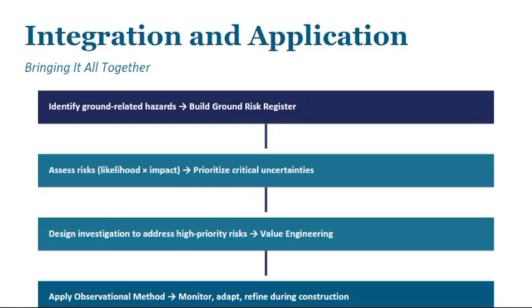case study, for example, of a proposed high-rise building on reclaimed coastal land. So this is the case study. They want to build a high-rise building on reclaimed coastal land. Now, let's evaluate what the potential risks are. One is going to be soft compressible soils. Yes, in most reclaimed lands in the coastal region, that's one problem you can encounter. High groundwater, right? Differential settlements. So these are potential risks you can predict.